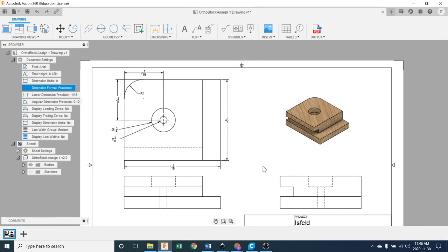So I don't need to add any more information, and that's another rule of dimensioning. We don't add information that's unnecessary. You don't duplicate information. So I've added the width of the block here at 4 1/4. I wouldn't add it anywhere else. Like for instance, it might be tempting to show that this is 5 1/16 here and show that it's a 5 1/16 down here, but we don't do that.